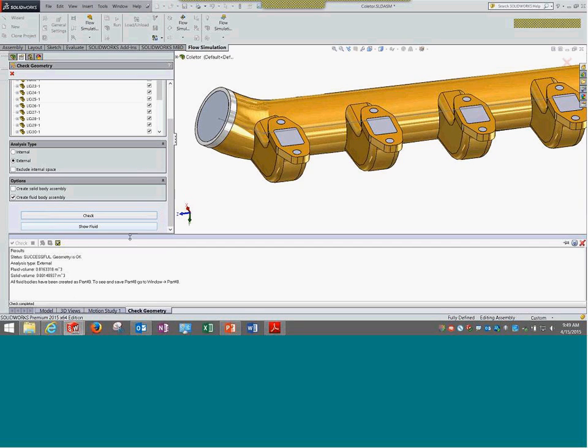Now take other software, like Fluent or CFX. The way it works is we invest a huge amount of time to create this particular fluid body, and thereon we just get rid of the solid geometry which you are seeing on the screen and do analysis on that fluid body. Whereas here, we are not even worried about creating that geometry.